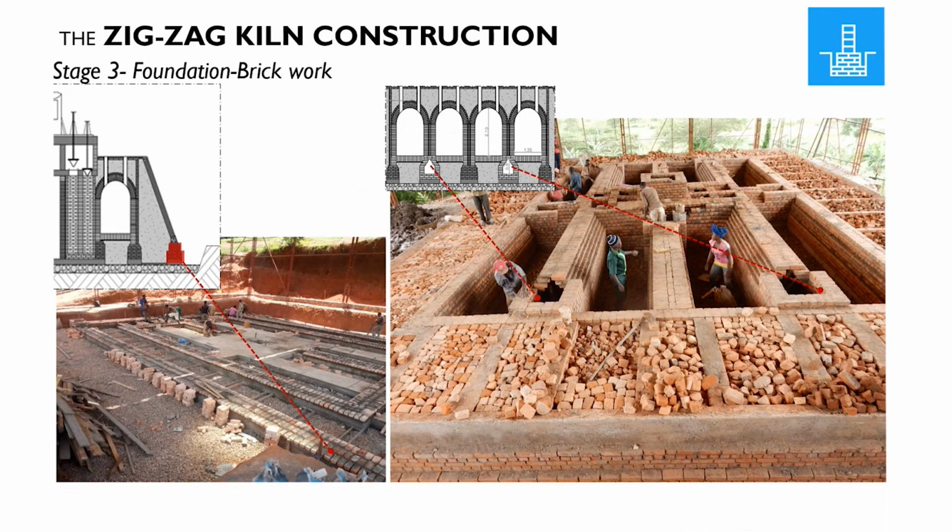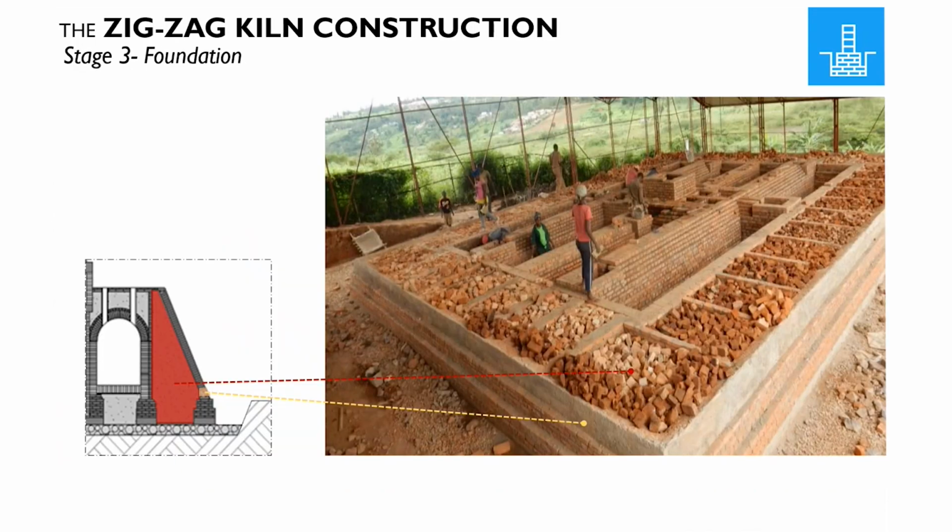As we are completing the foundation, concrete and the drainage substructure part, let's now start masonry work elevation, starting from the smoke tunnel that is built at the same time with external walls. Note that the refractory bricks and the mortar are the material used, while external walls use ordinary bricks of cement mortar. The zigzag kiln foundation construction is ended with a tie beam for tying together the foundation part.